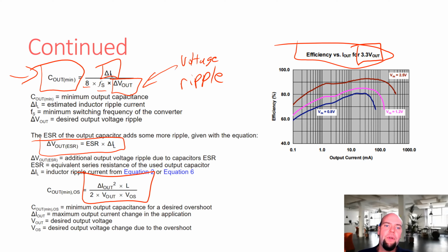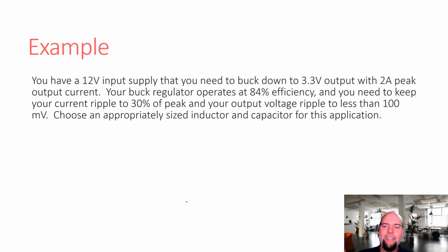So look at what the supply does when it goes to sleep and when it wakes up, because you could be getting an over voltage or under voltage event. And how would you fix that? More capacitance. Fork out a little dough, get yourself a better capacitor, bigger capacitor, lower ESR. There's no way around it. You've got to pay up. You don't want it to break down.